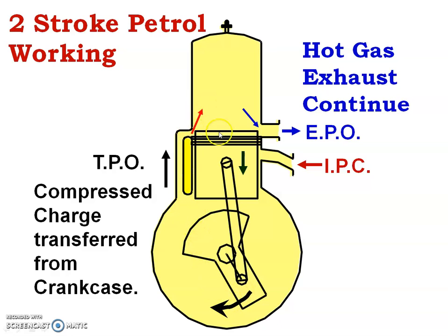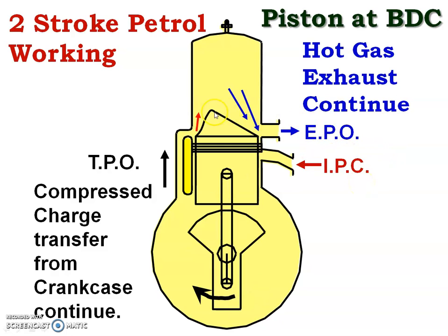Now you look at the shape of the piston. If the shape of the piston is flat like a four-stroke engine, then what can happen? From the left hand side, the fresh air and petrol enters, which can directly go into the exhaust port and be exhausted. To prevent it, the curved shape piston is provided. Due to that, the fresh air and petrol transferring from below the piston to above the piston moves directly upward, and the exhaust gases from the top enter into the exhaust port.